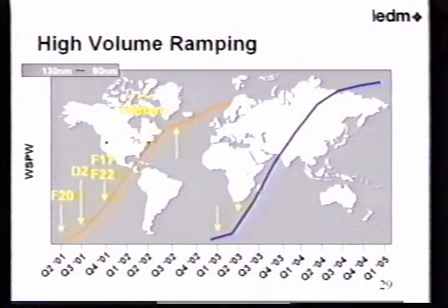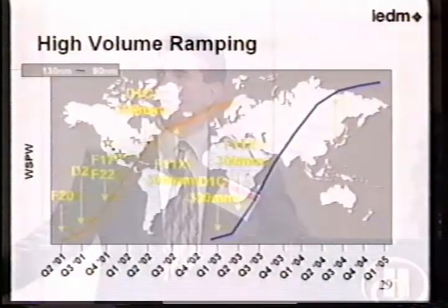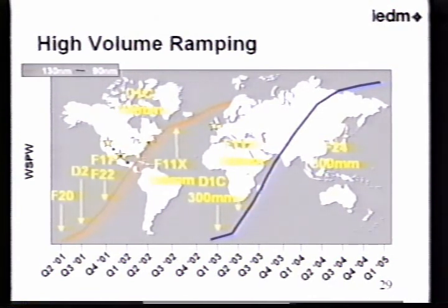If we look, for example, at Intel's deployment of our 130 nanometer technology, you can see how it takes us about 5 200 millimeter fabs and a portion of a couple of 300 millimeter fabs for us to generate the number of devices that are necessary in order to support the market. And you can see the ramp over time. If we look at the 90 nanometer technology, however, you can see that what was once done with 6 to 7 factories at 200 millimeter is really done almost completely with 2 300 millimeter factories and a little bit additional from a third 300 millimeter factory that we'll be bringing up in Ireland. The leverage is incredible out of 300 millimeter.